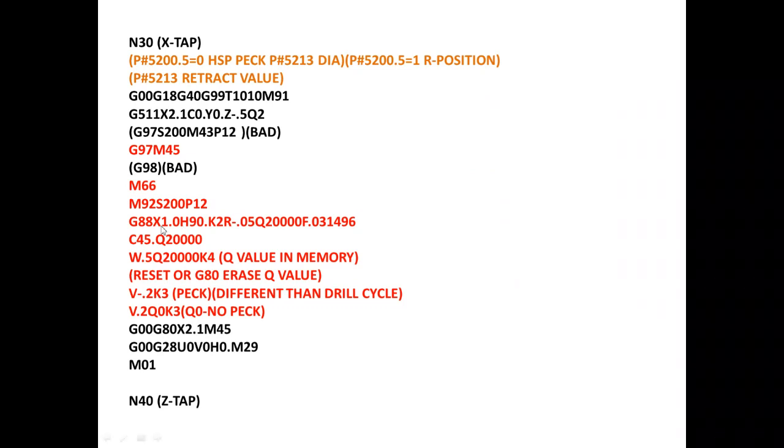And here's the format. Also many customers now, since we don't use a spindle, use a G99 inches per rev, and since the live tool is involved, many programmers automatically think it's G98 inches per minute.